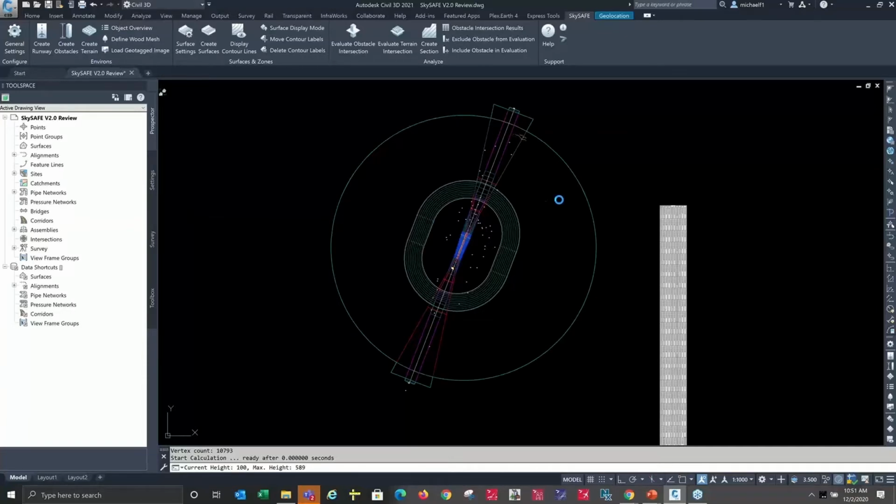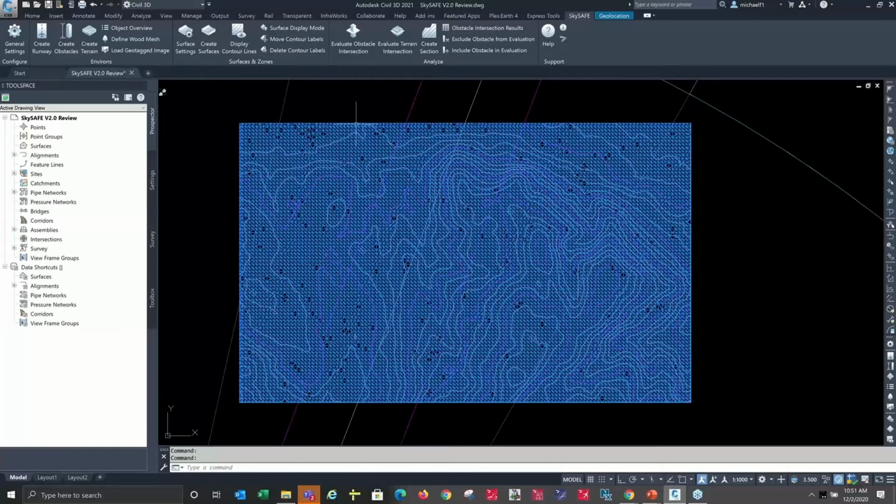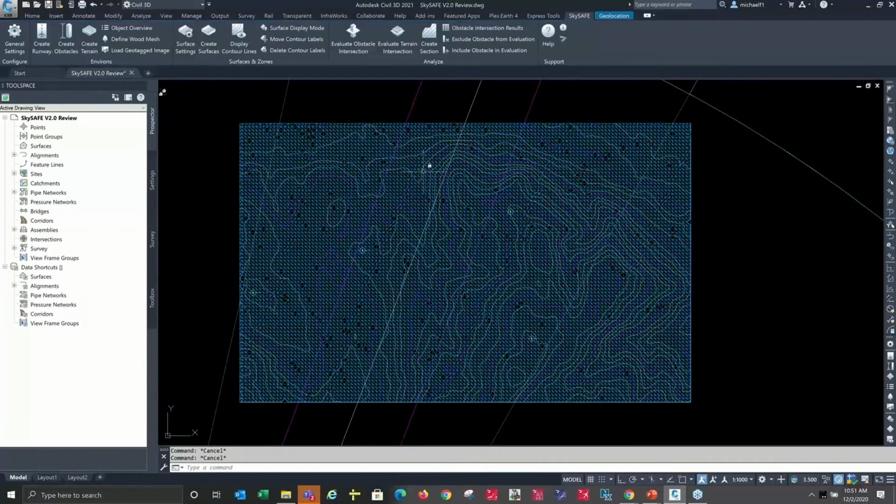There was actually 10,793 vertices found. It's building up the height and drawing it, so we're getting our contours being drawn. So this would work in AutoCAD or BricsCAD. That is not a vertical product that's intended to do grading and earthworks like Civil 3D is. So we have a mesh-based surface here with contours that makes up my terrain from my input elevation data.